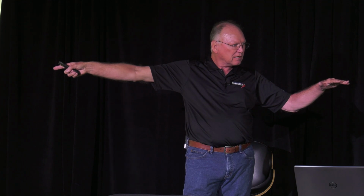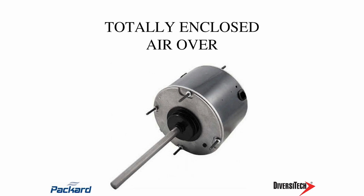But it's not. It's still bad, but my amps are going to be real low. And what makes it so bad is now the motor is operating so inefficiently that I'm putting so much heat in there, but I'm not getting the airflow because I'm restricting air. That's where the problem comes in. So those low amps are a problem as well as high amps. So these are air over motors. So the condenser totally enclosed, the blower an open motor.